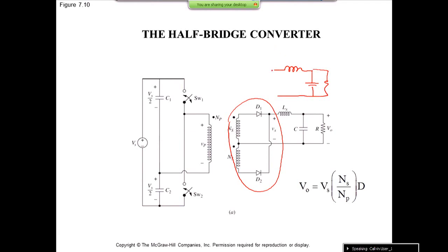All right, if you compare it with the buck, the right-hand side of all of these topologies is very similar to the buck. As it turns out, the voltage transfer ratio of these topologies is actually like a buck-type converter. So they're all isolated buck topologies.